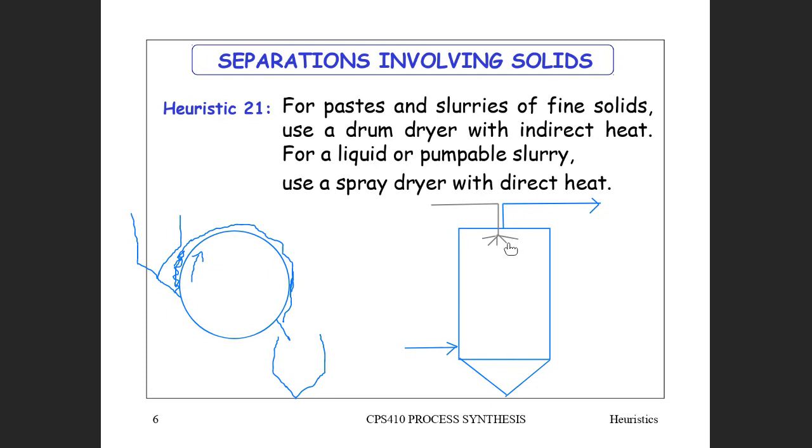If you have droplets that are too small, they can be carried out as powder with the gas at the top there. If you have droplets that are too big, they will fall too quickly, and then you might have some liquid, some water. They might not be properly dried by the time they get to the bottom. So yes, as soon as you have a spray dryer, the critical part of the thing is your sprayer, that it gives even sized particles.